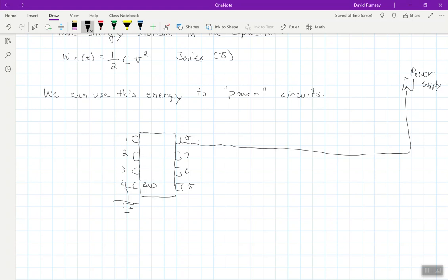Now what is often done instead is we say, okay, what I'm going to do is put a capacitor here. These can be somewhat large depending on the size of the chip, and sometimes manufacturers even tell you what size of capacitor you should put on these if you read their data sheets. I'm putting this capacitor, and on a circuit diagram I could put this anywhere, but I'm trying to show that on a PC board, this would be located physically close to the chip.